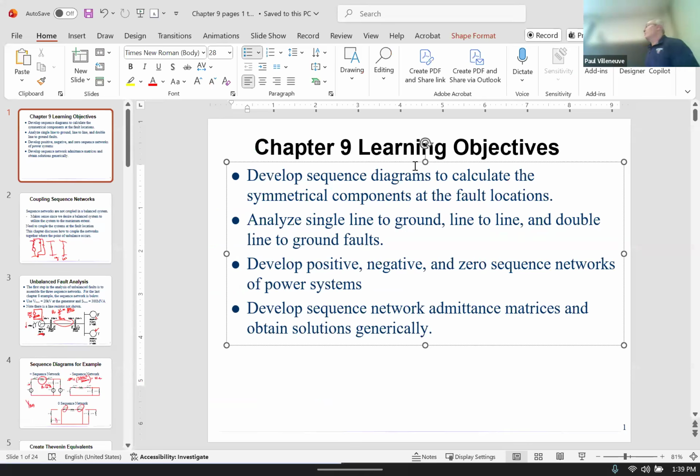Okay, questions on setting up networks? Because that's the homework assignment, right? Did you already see what the homework assignment is? Taking that system for the Dolby Power facility and figuring out which is the worst fault current, which bus and what is the fault. So that's where it's going to be very, very helpful to build your Thevenin equivalents and have your pre-fault voltages for an unloaded system and go through all that process.